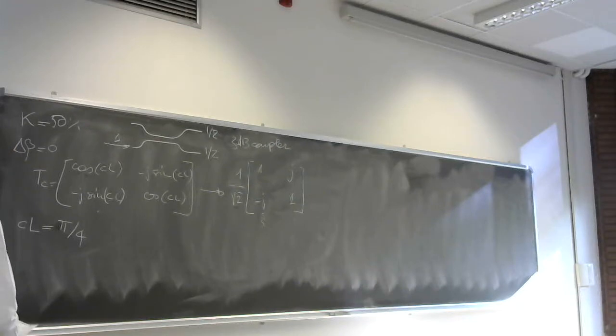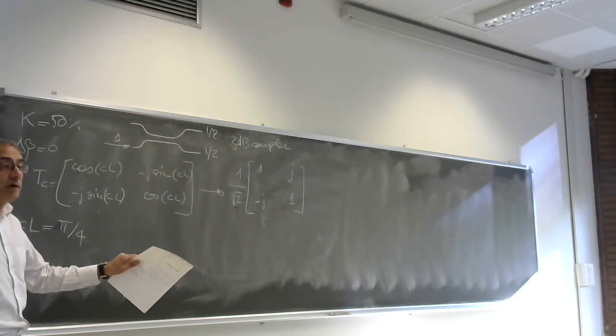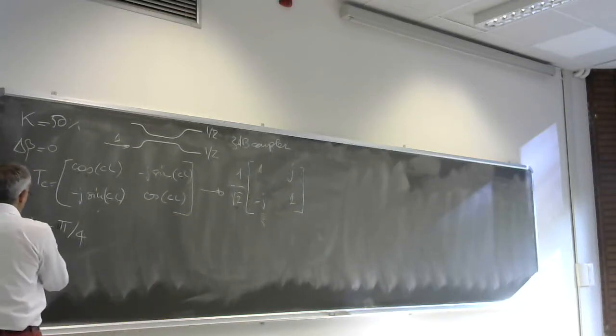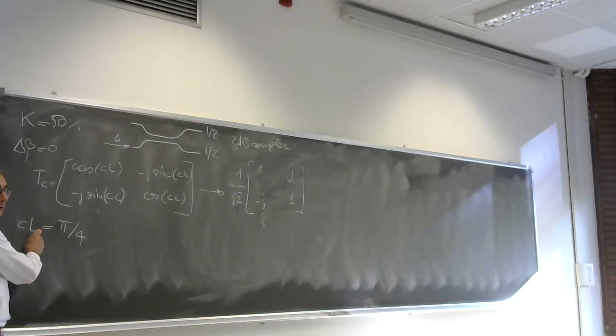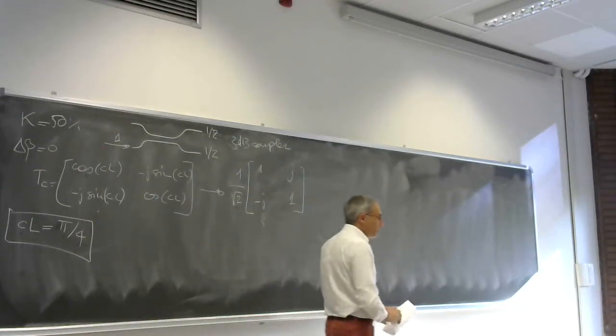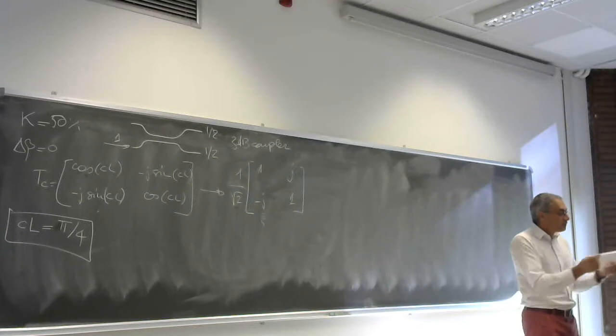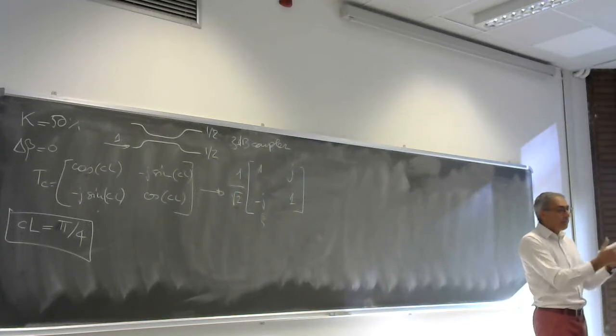So now, if you know your waveguide, so the exponential field outside of the waveguide, you know C, you can calculate L. So you see, you're not able in the design to calculate L and C separately, but the two always appear together as a product.